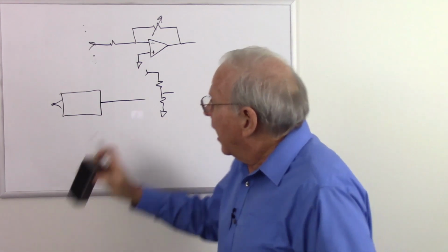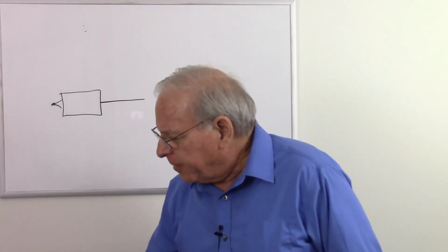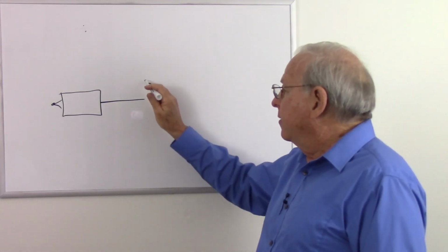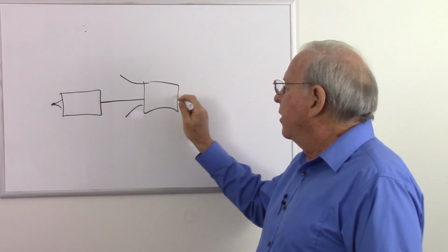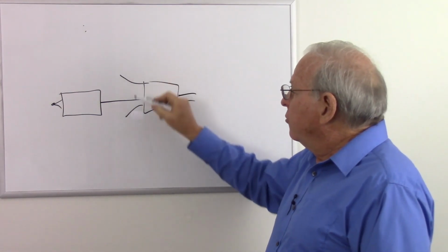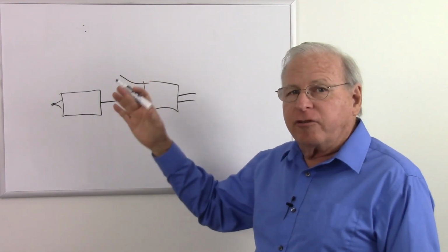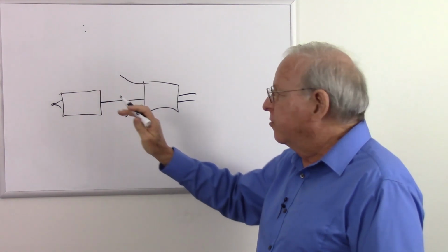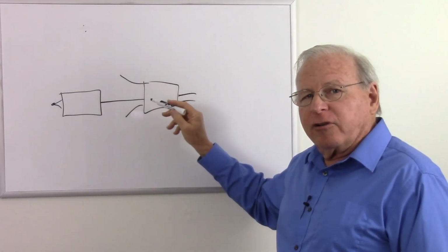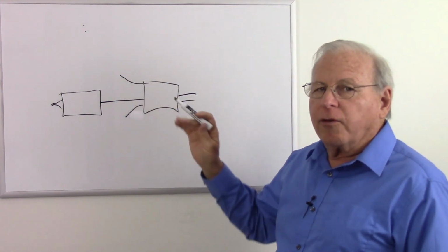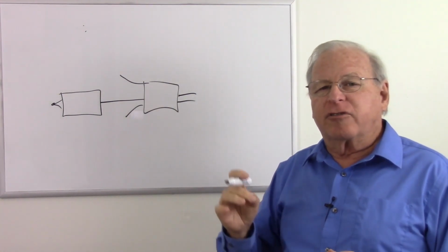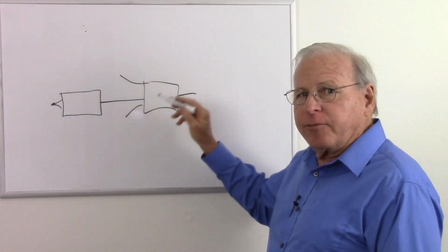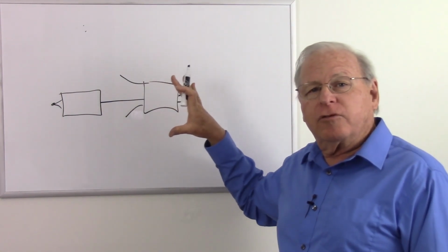And we can send this output into a computer and we can wire things together to multiply things, divide things, add things together, and get some other inputs into there and get a certain output or multiple outputs to do some particular job. Like I said, the circuitry is pretty simple. This would be maybe 1 transistor and a few support resistors or capacitors and whatever is needed to make that work. Each operational amplifier is like 2 transistors, although the modern operational amplifiers are integrated circuits and have more circuitry, but they're very simple. And so we can add, subtract, and multiply and divide, and we can even make circuits that will do square roots.